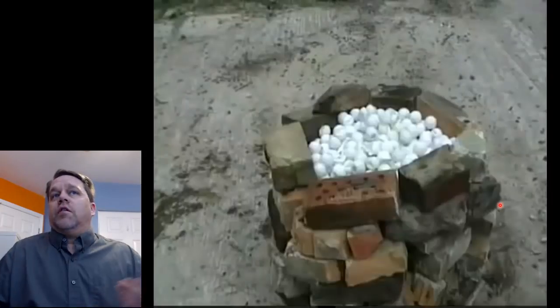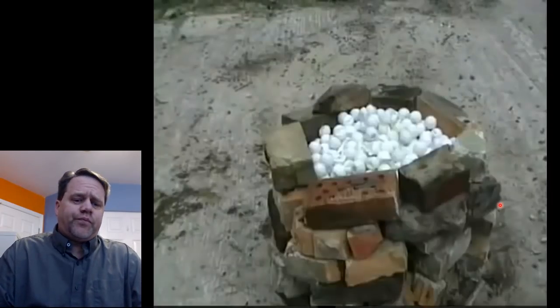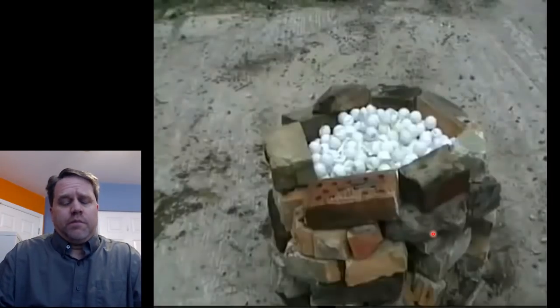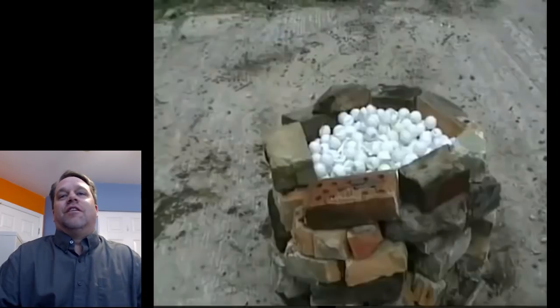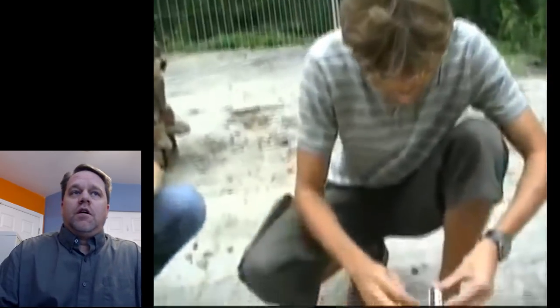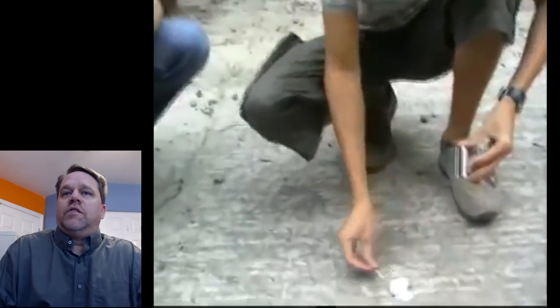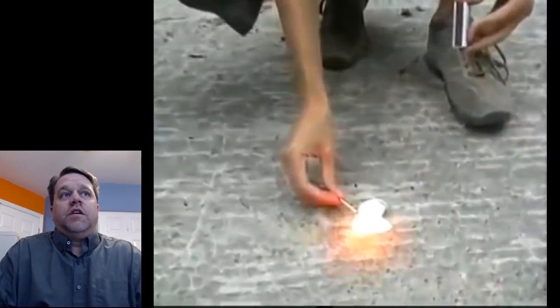There are special rules in Article 520 because of the dangers associated with nitrocellulose film. So nitrocellulose film is an example of a self-oxidizing compound, and believe it or not, if you've never had your hands on nitrocellulose, you actually probably have. Ping pong balls are made of nitrocellulose, and they're remarkably flammable, as you can see in the video here. That's just a regular ping pong ball.